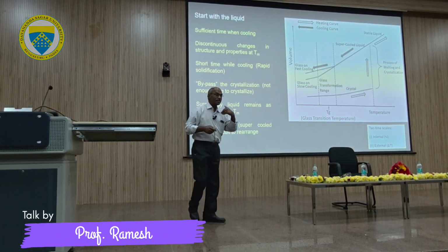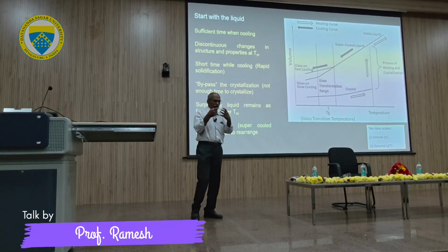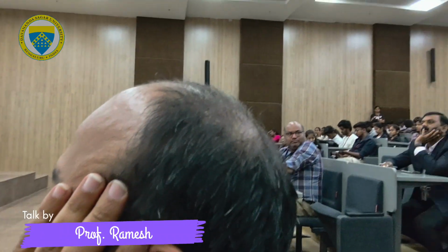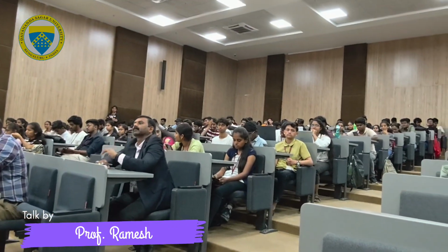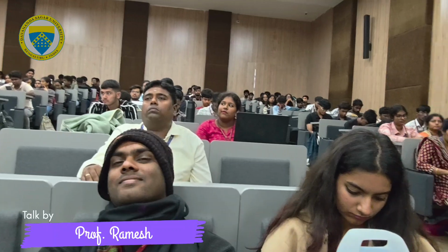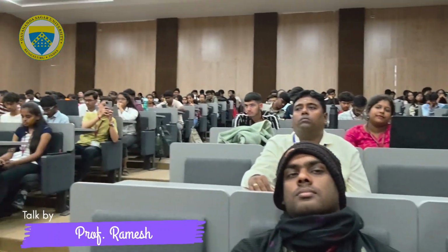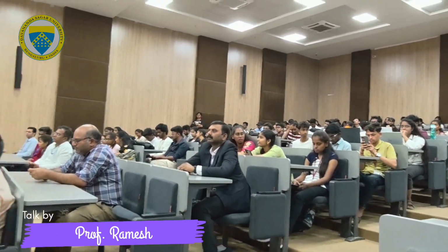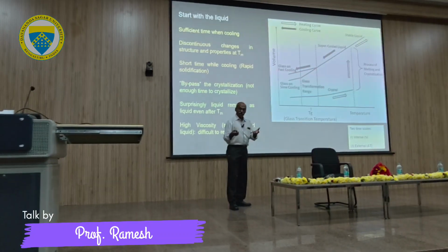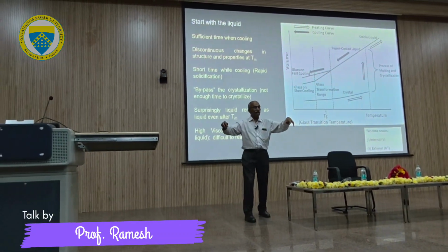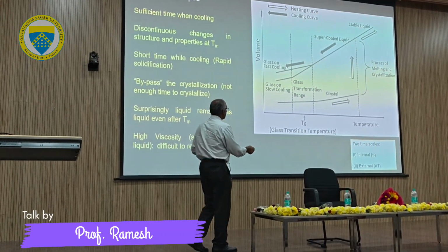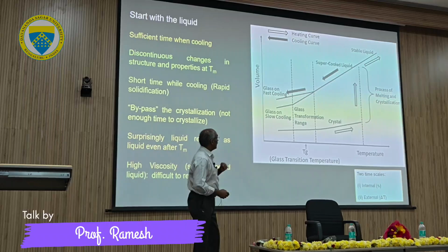When you decrease the temperature, you are reducing the energy, viscosity increases, and the atoms come closer and closer. They make a bond actually, right? Once they make bonds, they lose their energy, and once all the bonds are formed, there is a sudden change in volume. They become a solid actually, right? The first order transition, you can see. Because you have given a lot of time, they sit in the regular positions and take a periodic arrangement of atoms. So they go to a crystalline state, which is a low energy state, the equilibrium state, right?